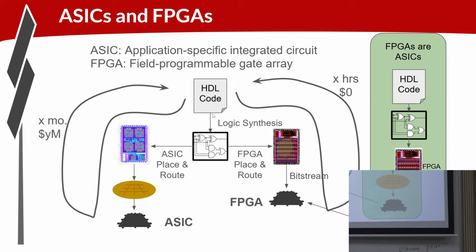Of course, you're giving up something, right? You don't have the flexibility with the FPGA that you have with the ASIC to optimize the circuitry. So you might lose about 10x. 10x area, 10x power, 10x performance, kind of the ballpark.